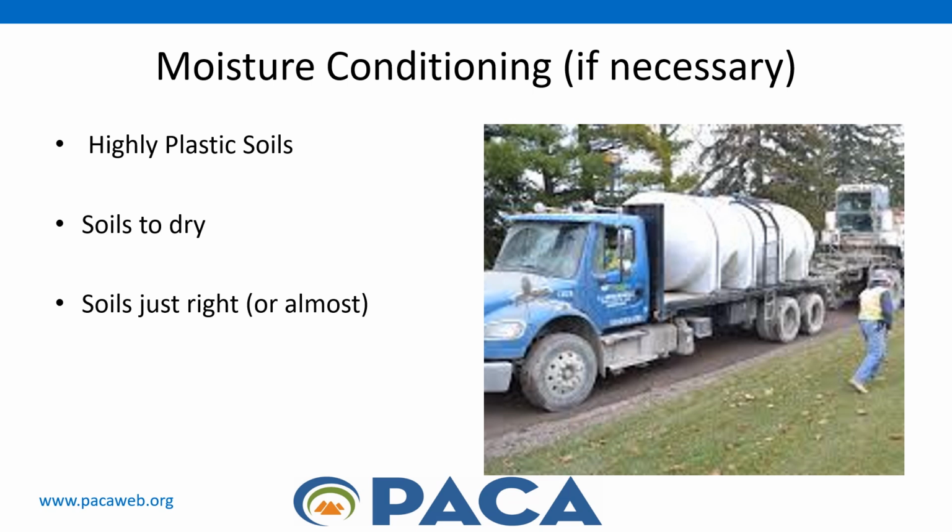The subgrade should be tested to determine the moisture content at the beginning of the construction operation. For highly plastic soils, mix the cement in dry or in slurry form prior to adjusting the water content to bring the soil to optimum moisture content. This may prevent the clay from balling and failing to provide the desired results.